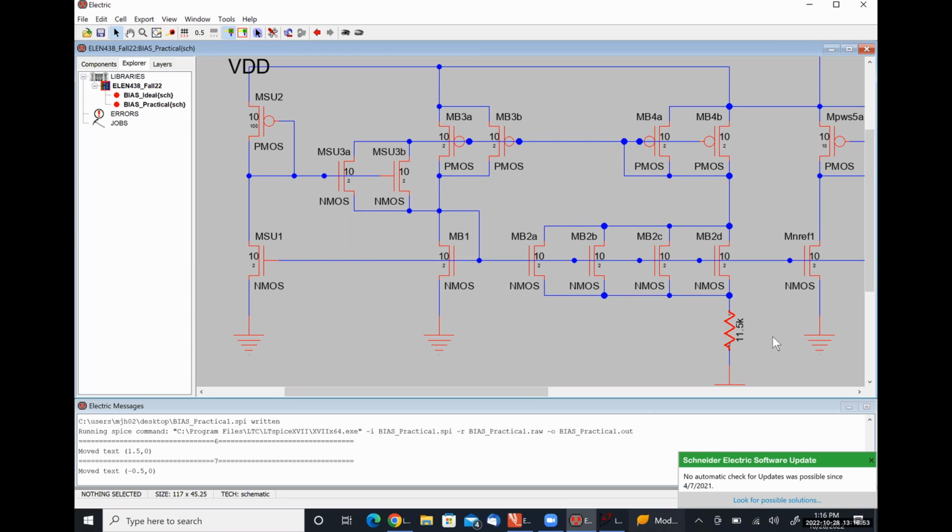All right, so it didn't give you errors there, so that's good. If you labeled things, just type ID, open parentheses, B1. It's case sensitive. MN or MM? For me, it's MM, because it's going to be M and then the label that you gave this transistor. I labeled it as MB1. I did as well.